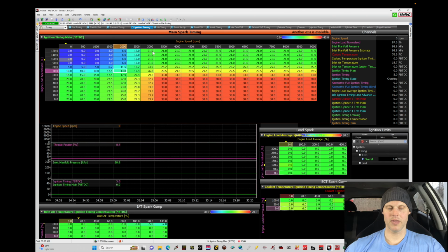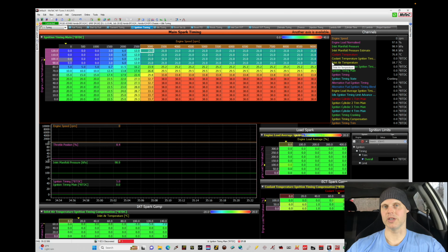Ignition tuning, we find that we had our optimized timing at 21 degrees. This will be a safe starting value because it worked on low cam. It'll definitely work on high cam, but we might further be able to refine and optimize this. Now when we engage VTEC, obviously we're going to have to share the same timing table with VTEC activated with this firmware package.